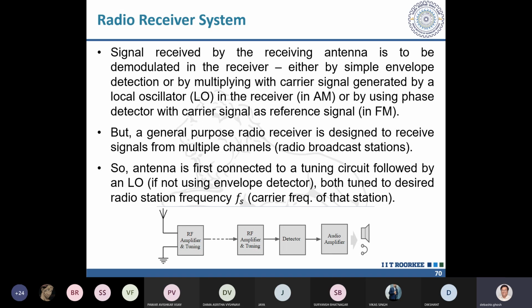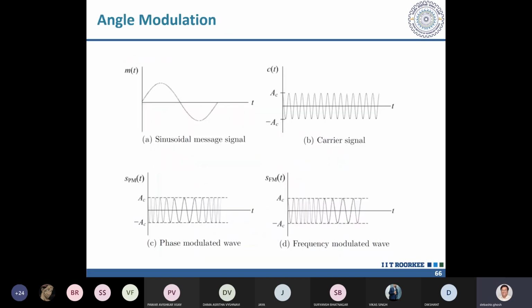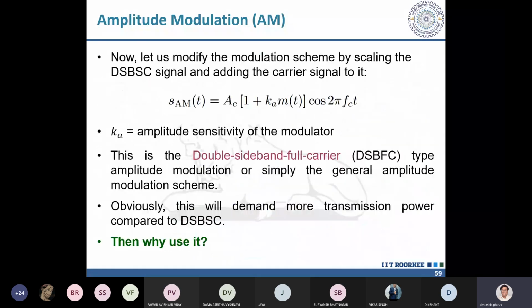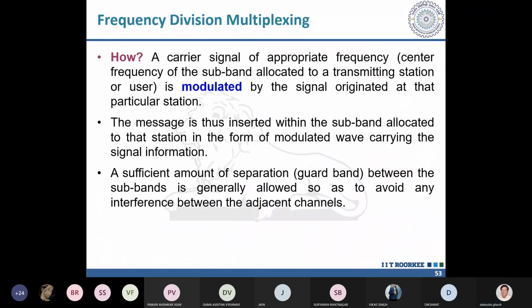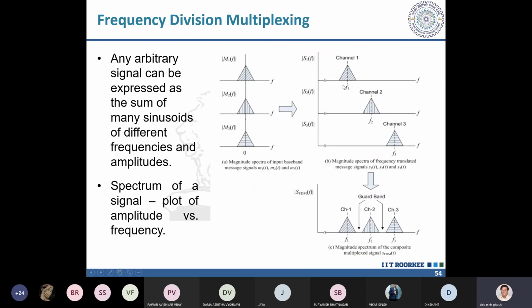So it is actually the center frequency, because, as I have shown in one picture earlier when I was showing the frequency division multiplexing, this is one channel. So basically this channel or the radio station is not just one frequency, it is a band of frequencies. But the frequency that we talk about when we say that this channel is of so and so frequency, you will always see that it is, say, 98.4 megahertz FM.